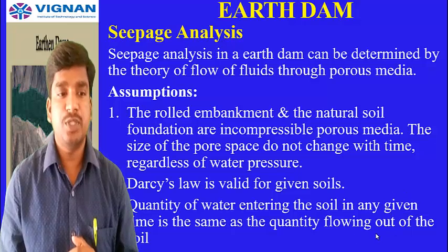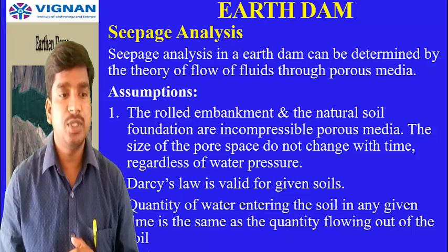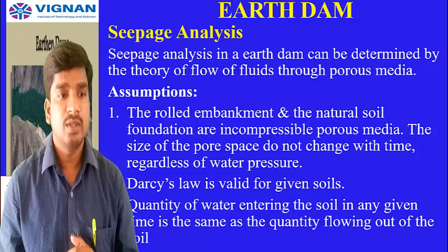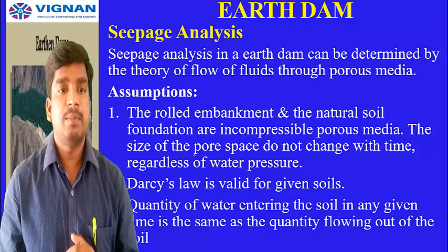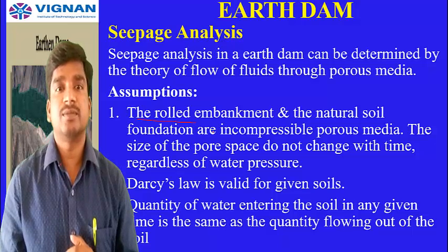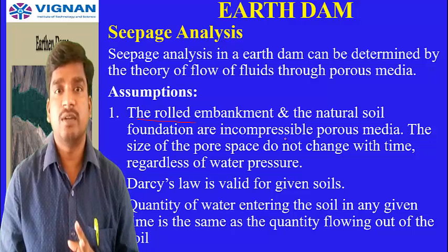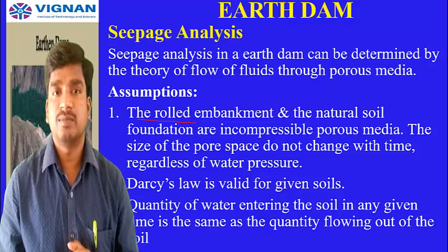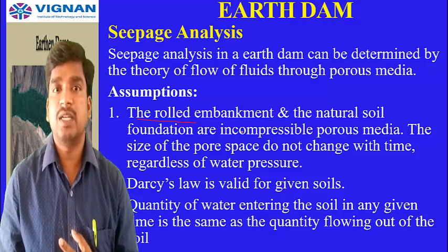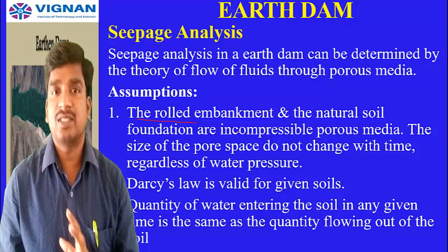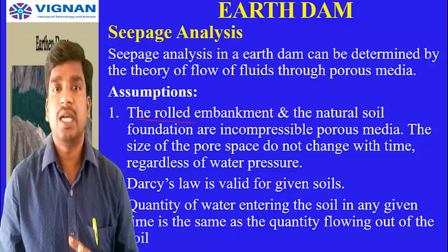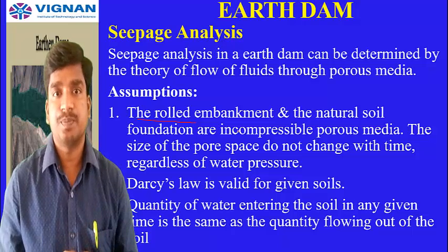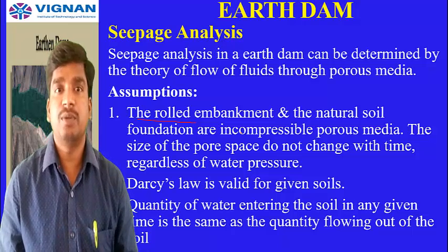Now, what is the first assumption here? The first assumption is that the rolled embankment and the natural soil foundation are incompressible. Whatever the embankment as well as the natural soil of the foundation, they are considered incompressible, as well as porous. That is the first assumption we have to make.